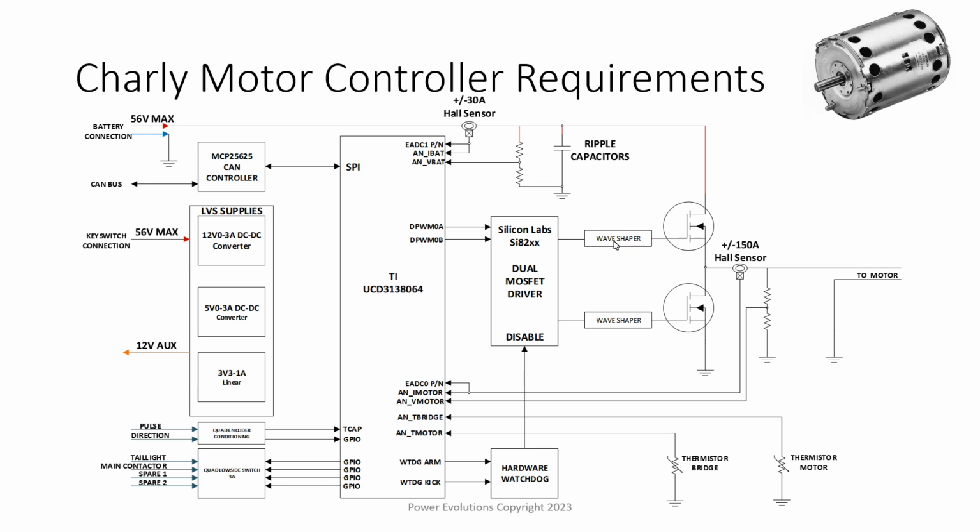So when you're trying to turn the MOSFET on, you can adjust the timing to be different than when you're turning it off. And when I get to the point where I start doing tuning of MOSFETs, I'll explain why that's important. But it has to do with the Miller capacitance and the charge injected into the gates, and also the voltage overshoots. And again, I'll go into that later.